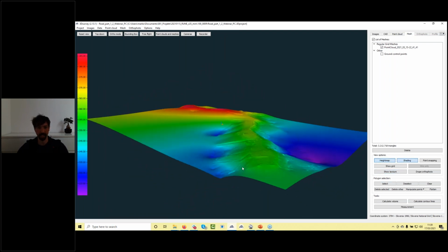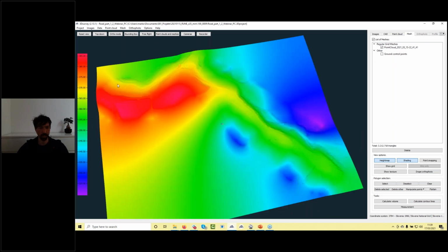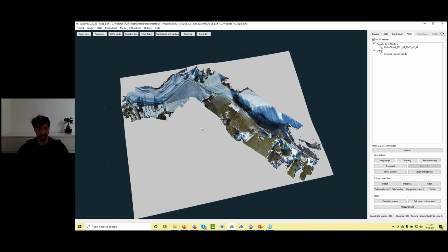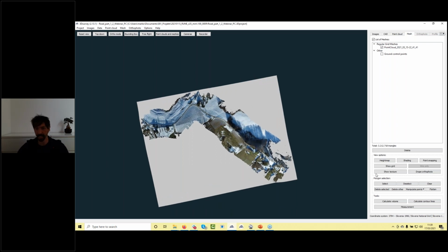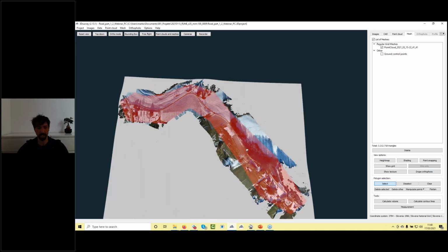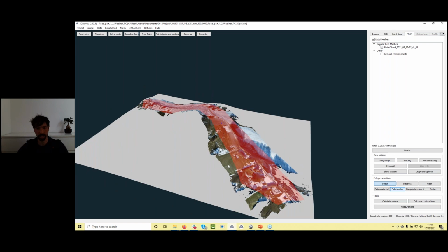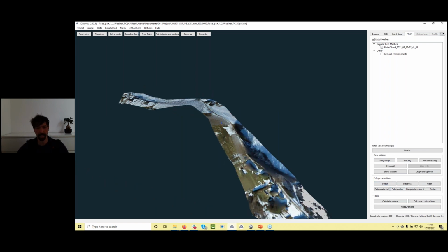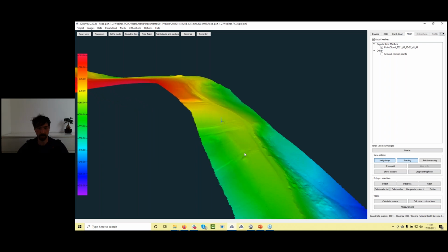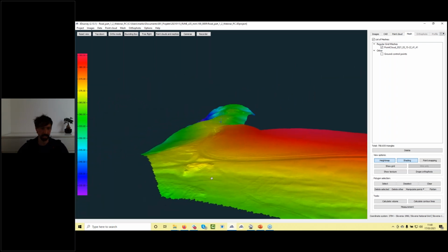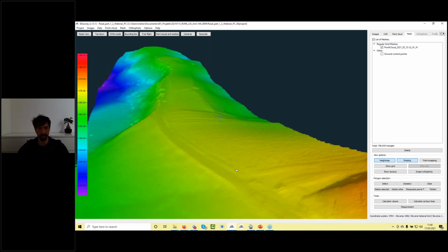As you can see it like so. The all interpolation gives me also those parts which I actually don't need, but I can easily fix this like so. I will go and select my area of interest. Okay, right mouse to finish the selection, and now just like before, delete other, and immediately I have my area of interest. Really nice detailed digital surface model with the regular grid.